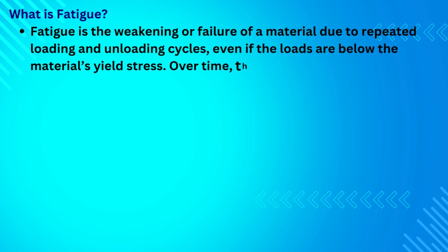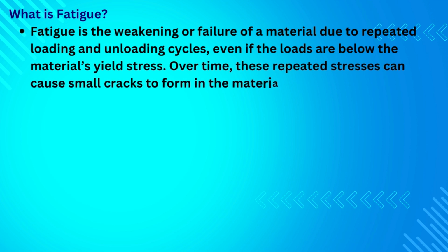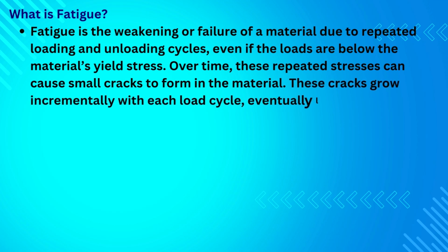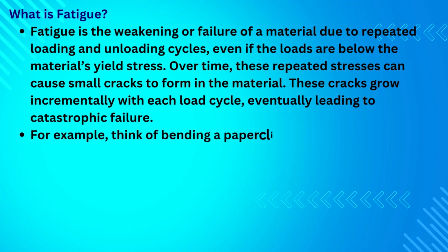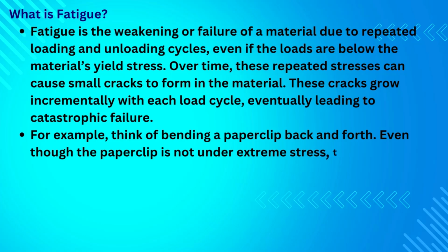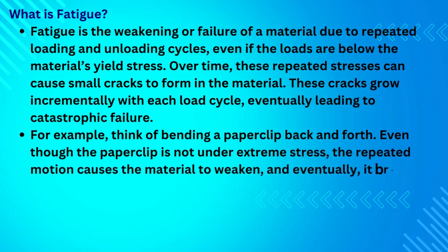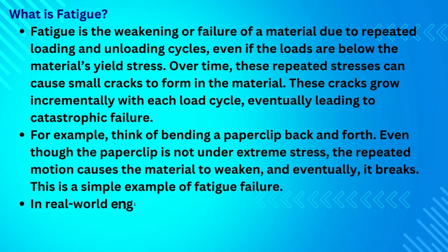Over time, these repeated stresses can cause small cracks to form in the material. These cracks grow incrementally with each load cycle, eventually leading to catastrophic failure. For example, think of bending a paperclip back and forth. Even though the paperclip is not under extreme stress, the repeated motion causes the material to weaken, and eventually, it breaks. This is a simple example of fatigue failure.